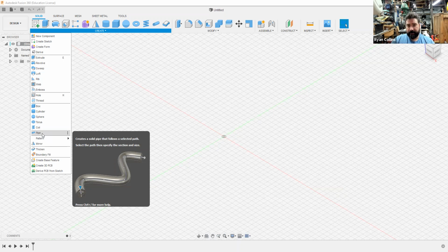What these both do is generate a body based on a created profile along a path. And a path is just simply a line. It can be a straight line. It can be like a fit point spline curved line, or you could even use some of the predetermined sketch designs like ellipse, square, circle, modify them from there, whatever, it doesn't matter. But you can generate between those.